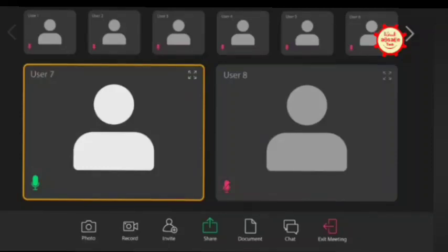In NACE you will only find how to avoid HIC. If it's a sour service, you have to follow NACE and do the heat treatment and all that procedure as per this. Correct. And after that, for testing, I don't think there is a clause for that in NACE. It's based on experience also. Based on your past experience, you have to ensure that this will not fail from hydrogen induced cracking.